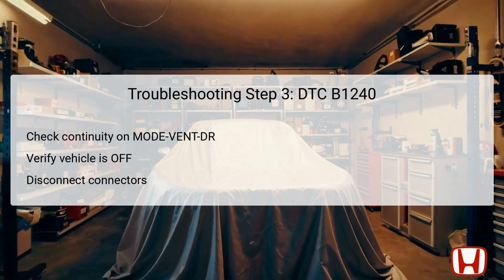However, if there is no continuity, this indicates a failure in this specific wire that must be repaired to proceed. Accurate verification of wiring integrity is essential for resolving the DTC effectively.